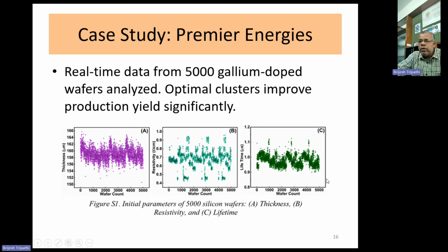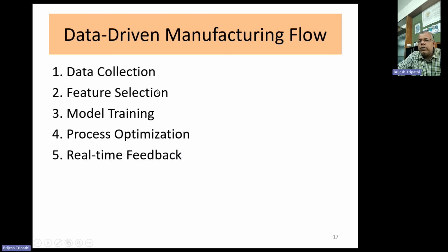One case study we have taken, data of the wafers as thickness, resistivity and lifetime. 5,000 wafers data was input for our study. And then we have identified some of the features. Then we did model training, process optimization, and then real-time feedback.